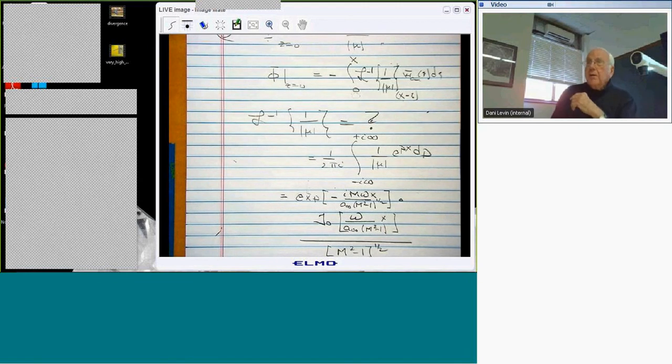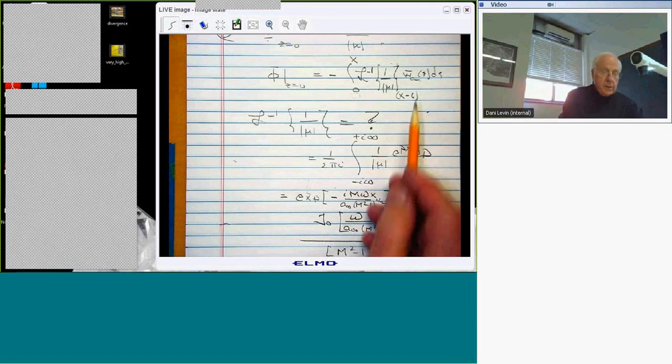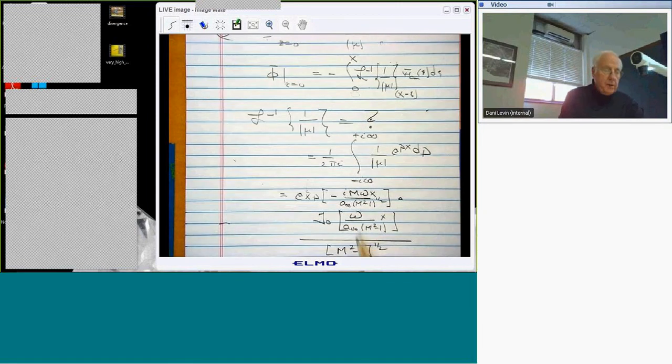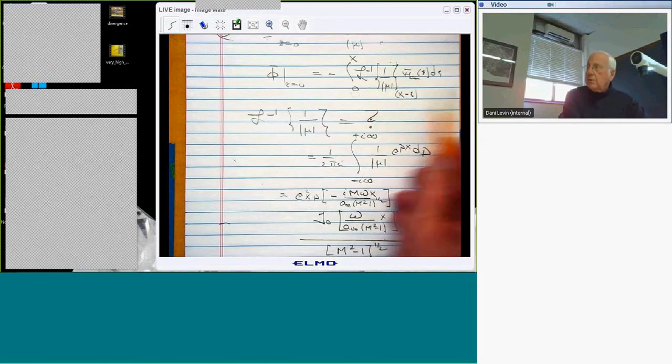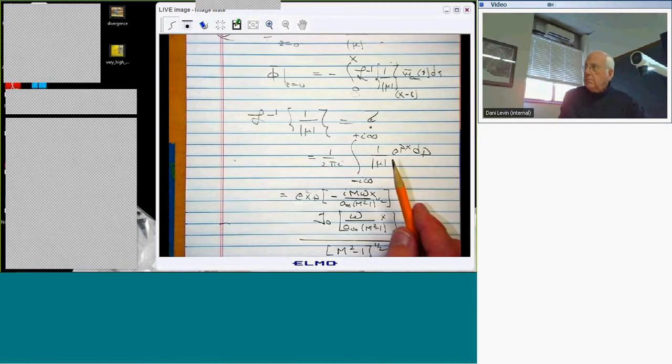Remember, this is the easy case. This is 2D supersonic flow. Everything gets harder after this, okay? But this is the easy case. So the nice thing about it is what at least a mathematician would call an analytical solution, right? We haven't done any numbers yet. We've got analytical formulas involving an integral with this combination of functions that we insert in here, and someone tells us what the motion is, and we perform this convolution integral. Some cases you can do it analytically, other cases you'd have to do it numerically, and out pops your solution here.